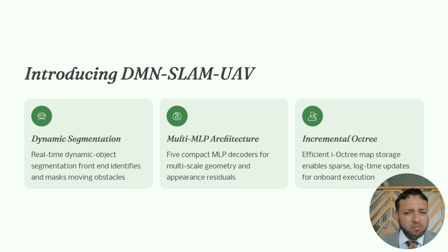Our system, DM-SLAM UAV, fuses a dynamic object front end with a neural implicit map and an efficient octree back end. The result is a SLAM pipeline that remains stable despite movers, reconstructs dense surfaces for inspection, and runs onboard in real time.